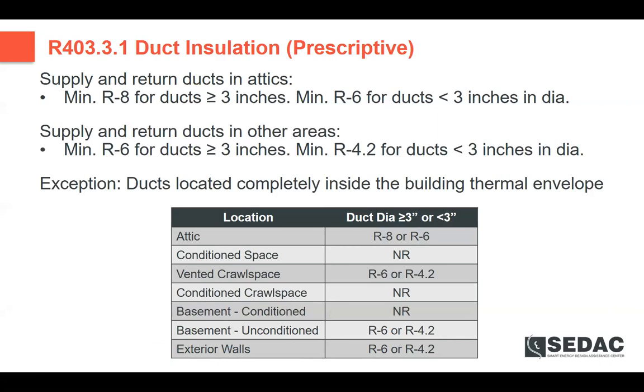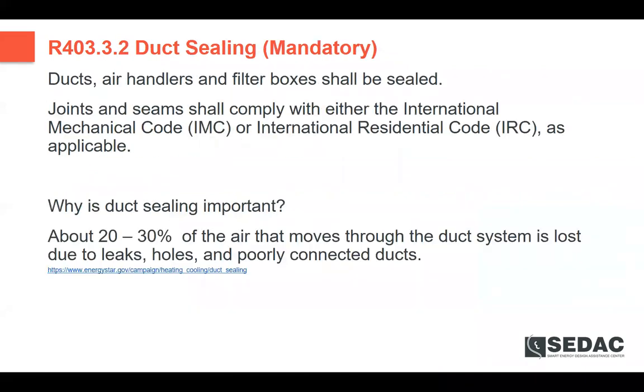If you don't have your ducts insulated, and this is where the detailing of installation performance really matters, if you insulated most of the duct but then didn't seal some of the seams, you could end up with moisture issues, which can lead to mold. So duct sealing, again, is mandatory regardless of your performance path, and noting that you are to seal all the joints and seams.